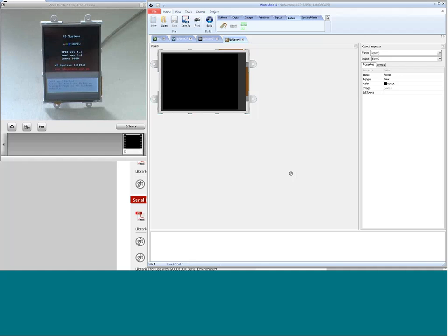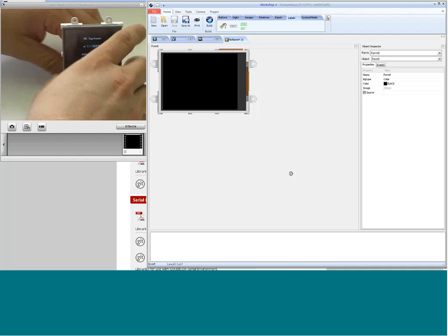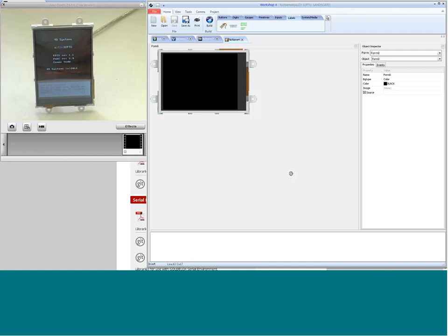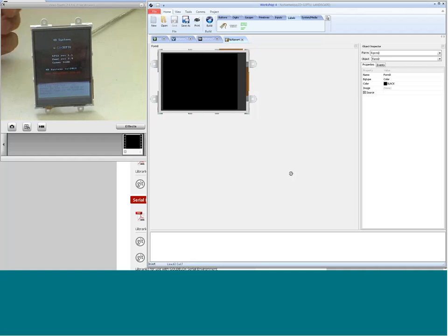Well, I can say something to this. The PICASO is a controller, like everyone else, even your host. Maybe your host is more powerful. Maybe your host is not so powerful, like a 16F PIC, for example, or an Arduino board, anything which is rarely able to handle display language. But this is actually able to handle I2C, 2 serial ports. You have lots of IOs you can use, so you can write a whole application just using the display. You don't need a host.